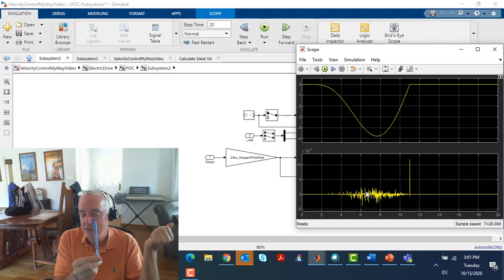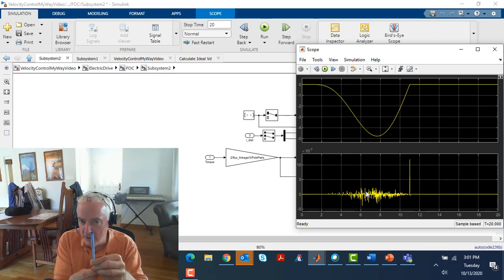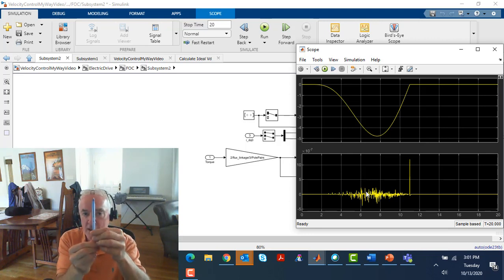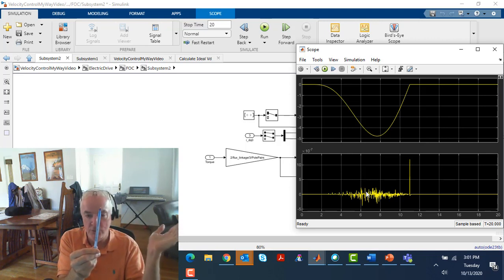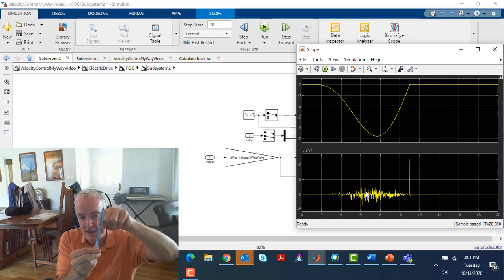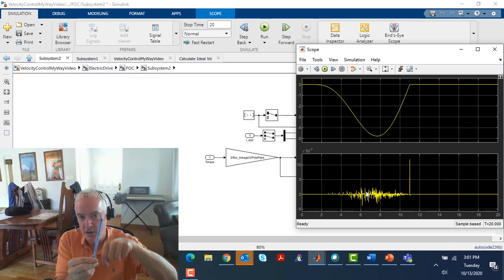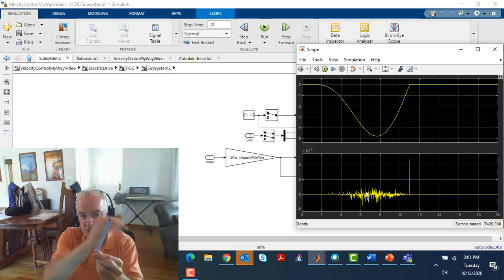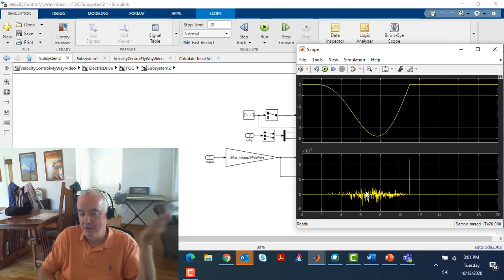We know that something kind of magic's happening. All right. And we know that because we kind of know that naturally it's unstable. That as soon as it starts to tilt, and if you apply zero controls, you're going to begin to get a gravitational torque. And not only that, that gravitational torque is going to accelerate it even further, such that the gravitational torque gets even bigger. It's kind of the classic definition of an unstable system.